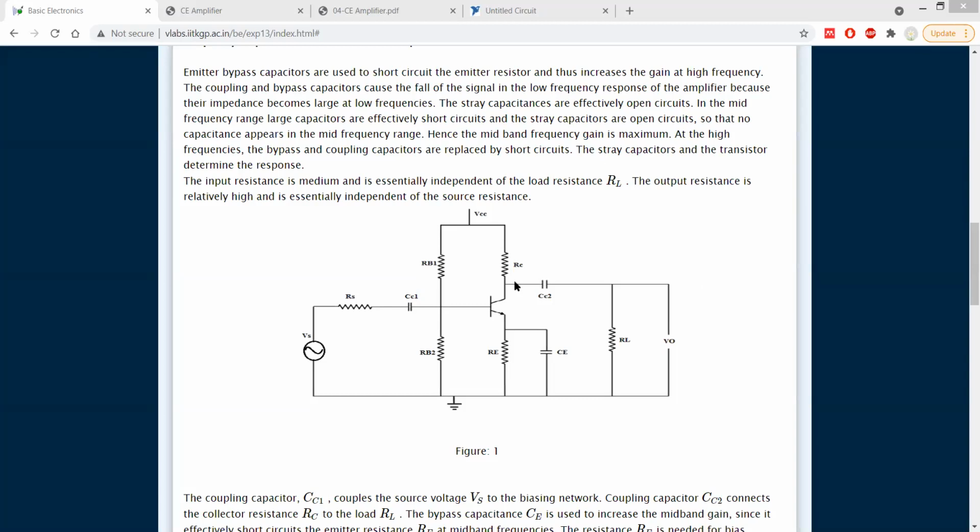Anyway, so what we are discussing is the basic property of a signal, that is amplitude and frequency. If you have applied, let's say, a 50 hertz and 1 volt signal, the output depends on the gain factor. Gain means the ratio at which you will have an amplified version. So if you have applied 1 volt and the gain is 10, then you should have 10 volt as the output. That's the simple meaning of gain.